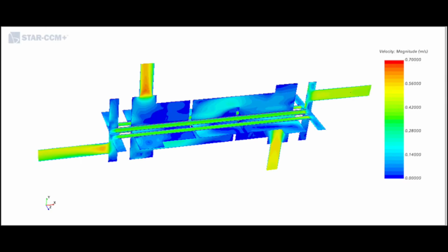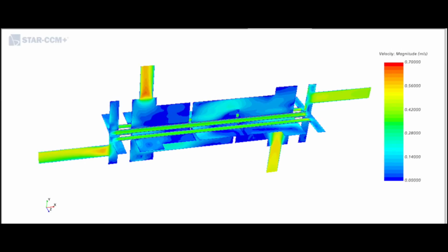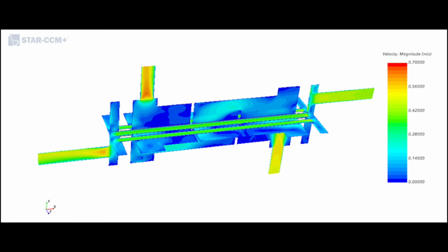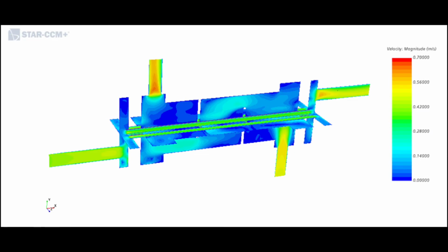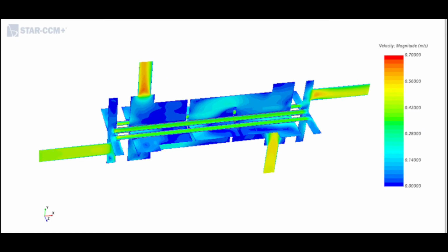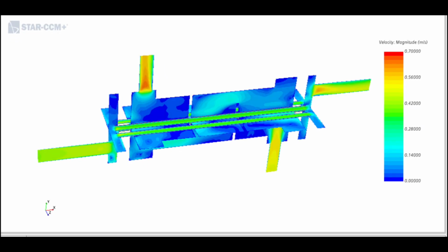Three simulations were carried out in parallel and three in countercurrent, with temperatures of 55, 60, and 65 degrees Celsius, and volumetric flow of cold and hot fluids set at 3 and 3.5 liters per minute, respectively.